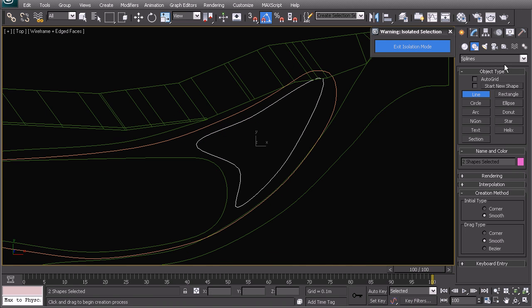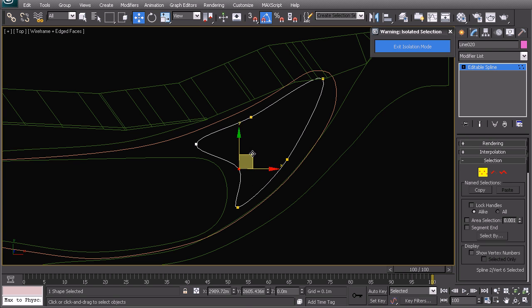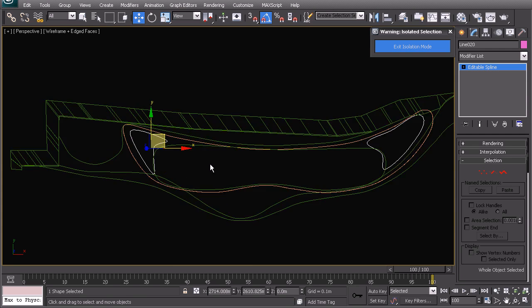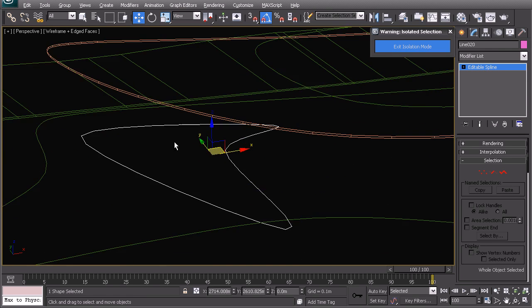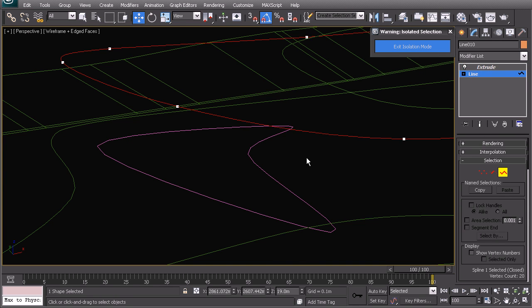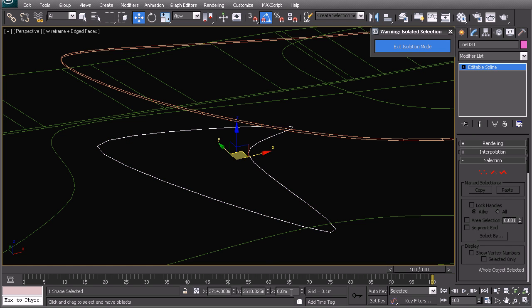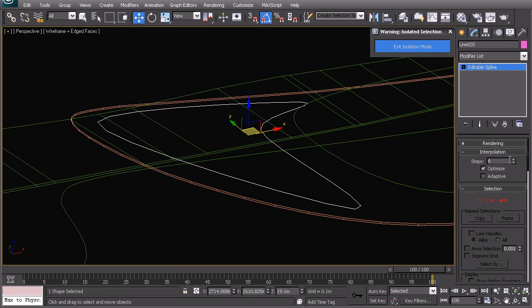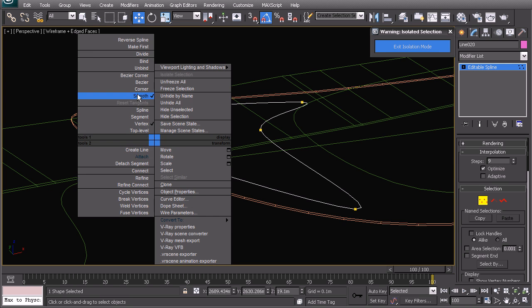And always with these splines, remember the fewer points you have, the better. Let's make this one a bezier and stretch it out a little bit. Great, so now that you have that, you can go into your perspective view, and we just need to find out how high this slab is. We can see here that it's 19 meters. So let's go ahead and move this up to 19.1, just so that it's sitting slightly above. That is smooth.